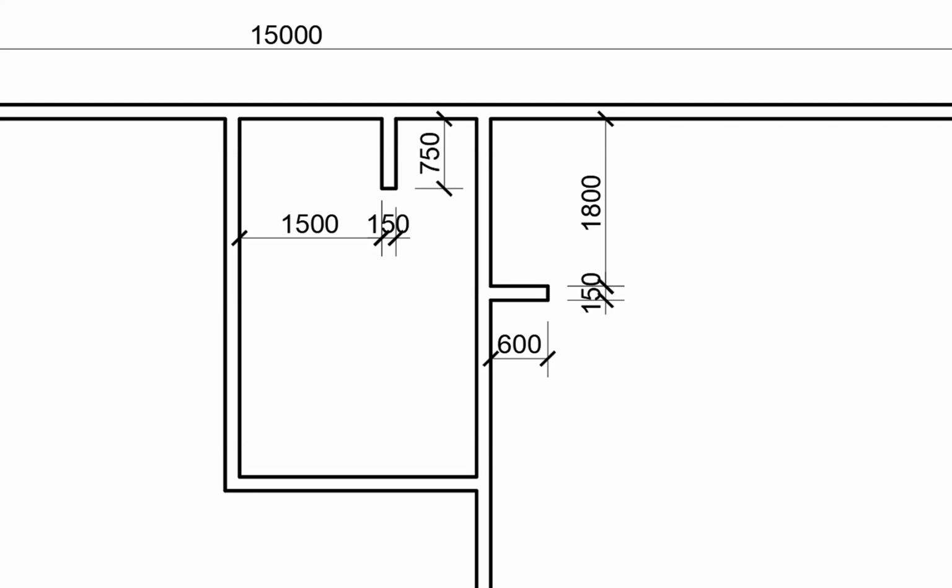So sometimes people will put in some little half wall that you might build in your kitchen up to a point, or some other places. You don't need to have a foundation for those walls. Just the walls that are carrying those main load from roof all the way down to the ground, you would target. So the bedroom walls, the bathroom walls, you know, the main walls for the building, for the rooms.